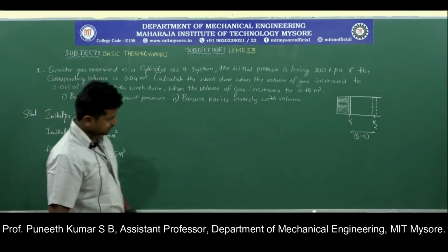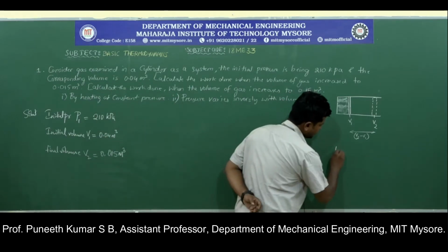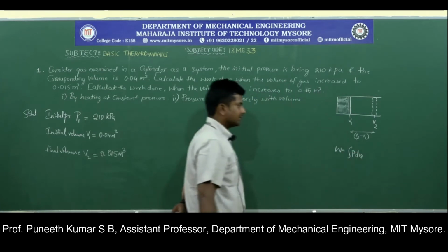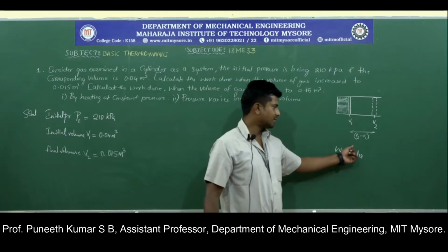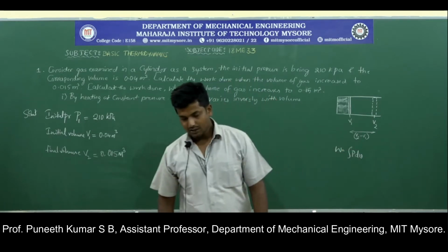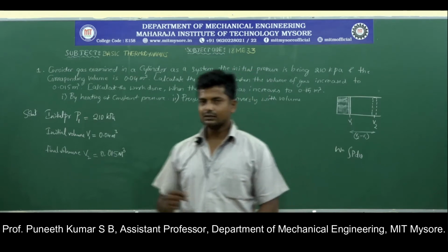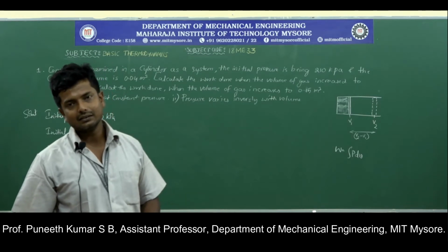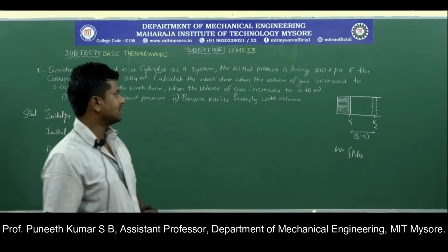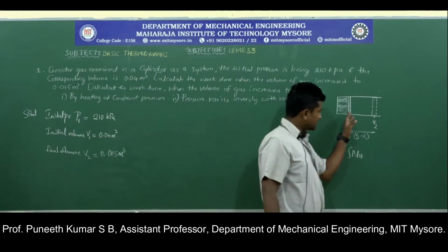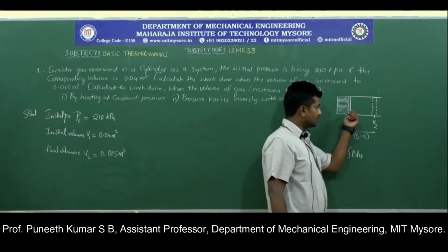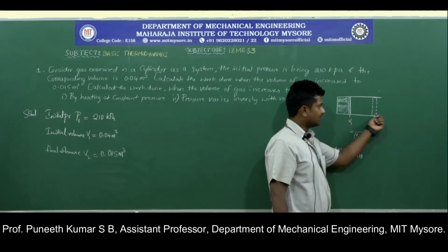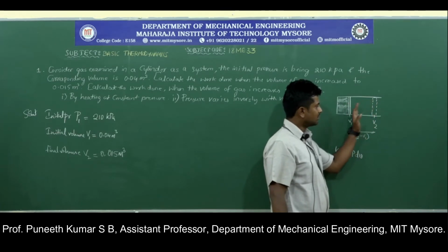We also know that the work definition is the integral of PdV. Here we have not written the limits, because work done and heat transfer are both path functions. In this problem we clearly understand that the position of the piston is the same, that is V1 and V2, and the displacement of the piston is also the same.